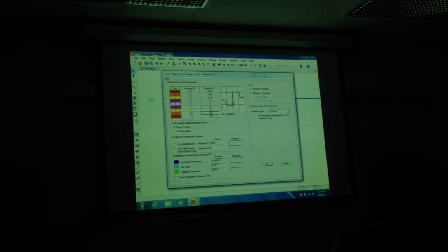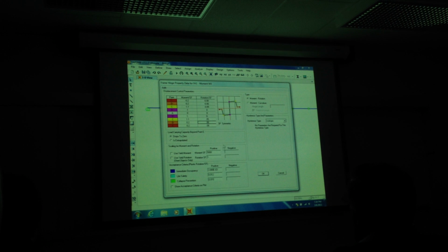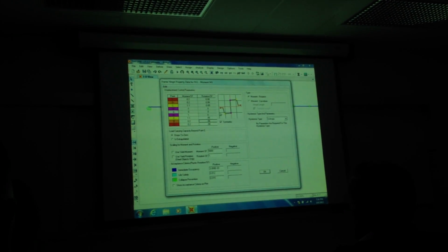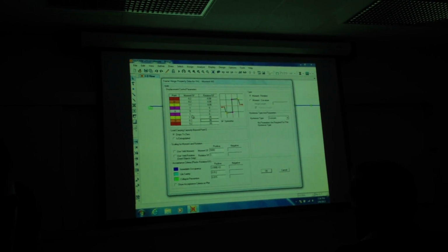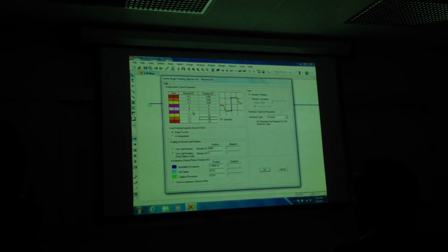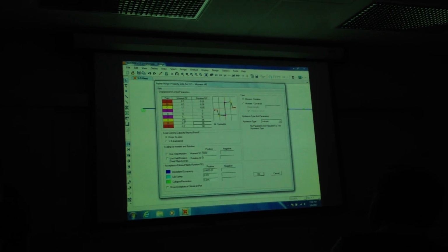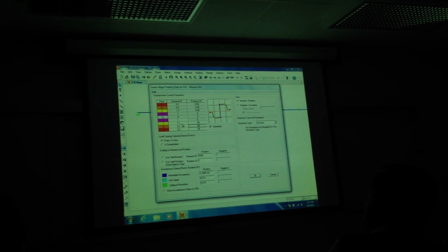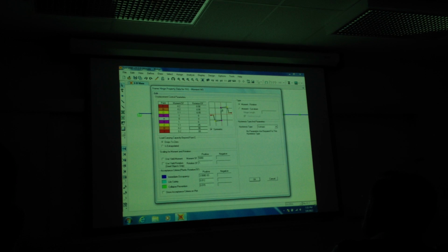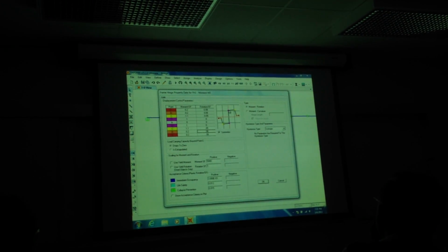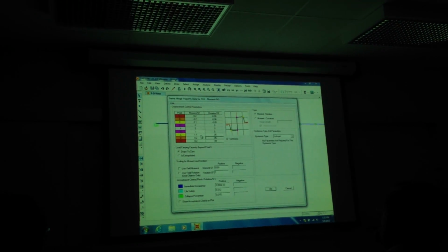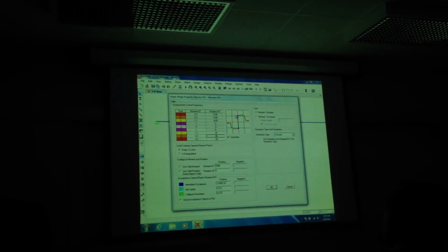This isn't the cyclic behavior, this is just an envelope for the cyclic behavior. It'll go up until it reaches this point, that's the 5,000. And you look at this, it says moment over SF. This is the SF. So at 0, that's that point right there. And then at 1, it's also at 0 rotation. So 1, this is moment over SF. SF is 5,000. So really, this is 5,000. It's just so you don't have to type in large numbers here. You can put one number here, and these are just ratios. And then this is 1.1 or 10% larger. So that's 5,500 kip-feet. So it goes up on this graph here. This is 5,000 kip-feet, if you just push them monotonically, not cyclically. And then if you keep going, this yellow point here is at a plastic rotation of 0.05 radians, and that's at about 5,500, 1.1 times that. That's what this is saying. And then it fails and it drops.